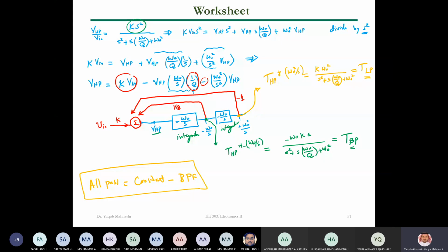It's just a matter of playing around. It's like you had a toy and you keep playing with it, left and right. So it is the same thing. You are playing with the same filter. So that's why we call it a universal filter. Okay. So with the two integrator topology here, we can get all types of filters in the same structure. Okay. What will be the gain, guys, for the band pass filter, by the way? What is the gain here? Of course we know omega naught is given, Q is given. What is the gain here?